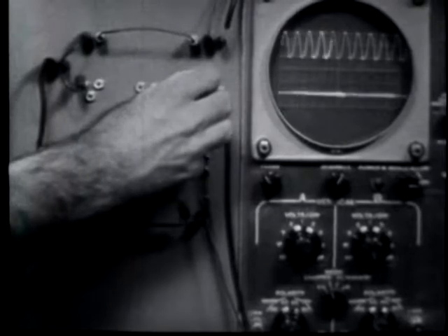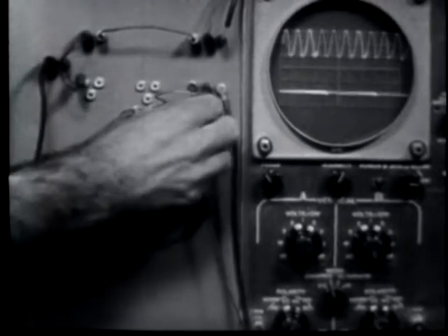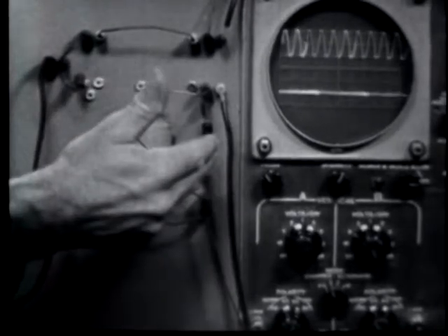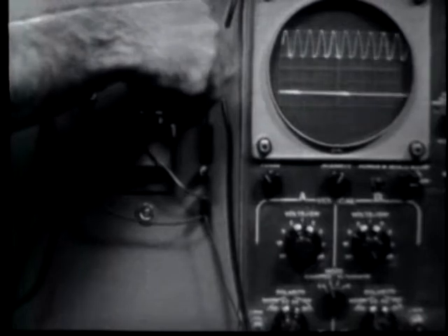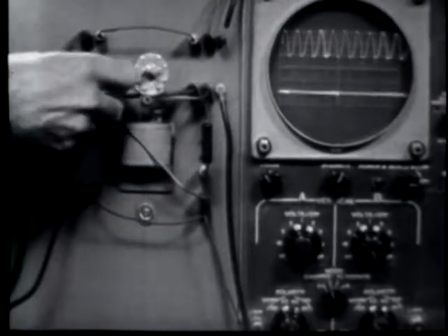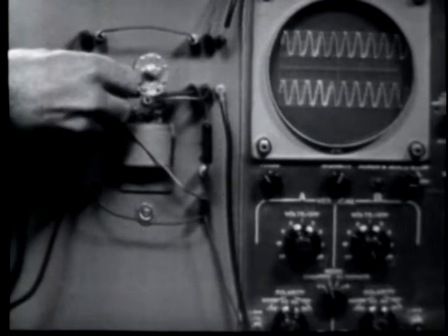So we'll put the inductor in here, just like that. Now, there's the inductor. In parallel with that, we'll hook the capacitor, just like that. Now, there's our parallel tank circuit. Now, we need a resistor to complete the circuit, and we'll use one of the resistors that we used in the first lesson, variable resistor, set to the correct resistance to operate the circuit. Now, just get it plugged in there now.